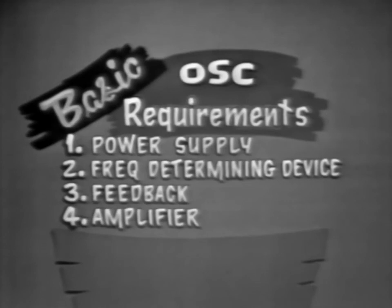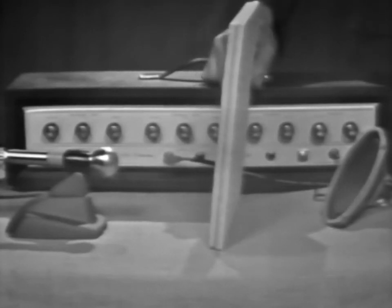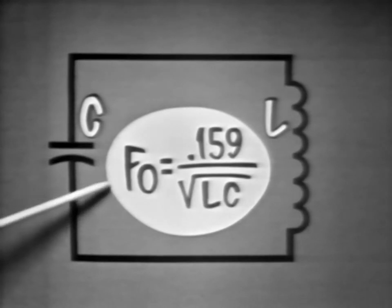Next, a frequency determining device. We have seen that an amplifier will oscillate without a frequency determining device. But the frequency is determined by distributed L and C, which makes frequency difficult to calculate and erratic. This kind of oscillation is usually undesirable. A frequency determining device, in this case the LC tank, provides a stable, easily calculated frequency.